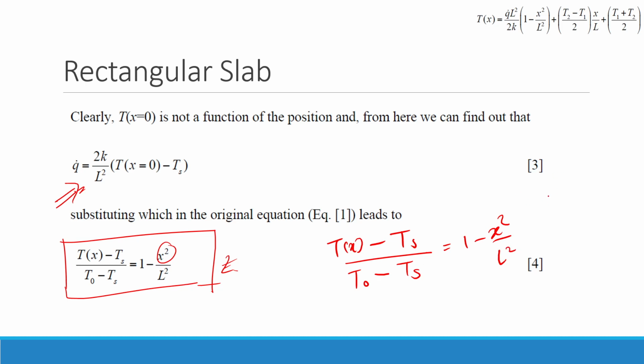So remember that this equation is only valid when you are having a block whereby uniform heat generation is occurring from the center, and the temperature of both the surfaces are same. So these assumptions you need to remember.